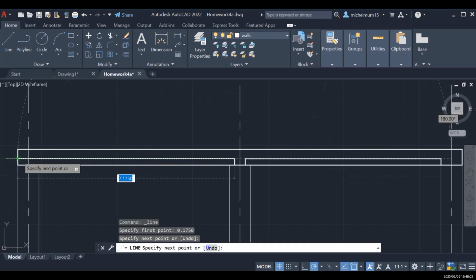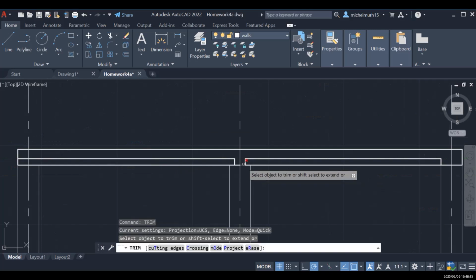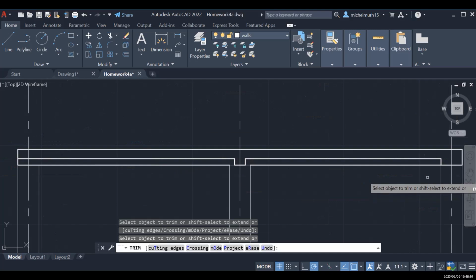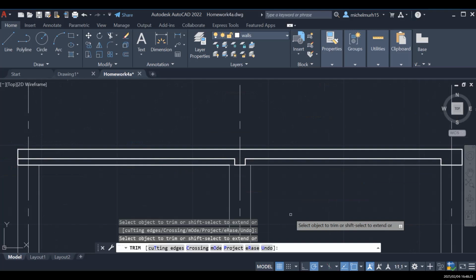So I'm gonna trim. Don't worry, guys. Don't get confused. And then I'm gonna put it in here. So first of all, before you get confused, I'm gonna trim some lines here. I'm gonna call the command trim, and then I'm gonna delete these lines, this line, and also of course this line. Okay, so I can also go to the other parts.